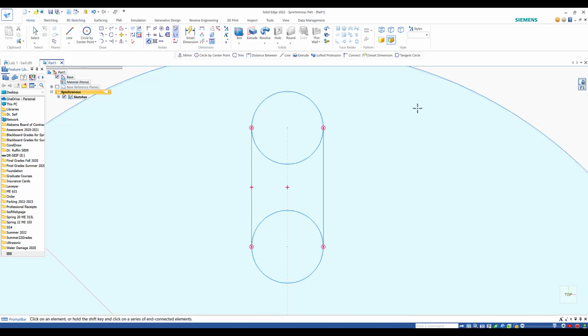Another item that we did, you remember that we locked ourselves to the top plane, and we see F3 here. Why will this help me? Because you see this trim here. If I click on the trim, I can use this quick trim: I move my mouse like this on the top and the bottom, so I get rid of the extra stuff I don't need. Any item I don't need, you just move the mouse on top of it. If it's not locked, then I have to identify the line and click on it. If I do the trim, I can do it either one by one or very quickly. This is a good practice, so I prefer you to do that.